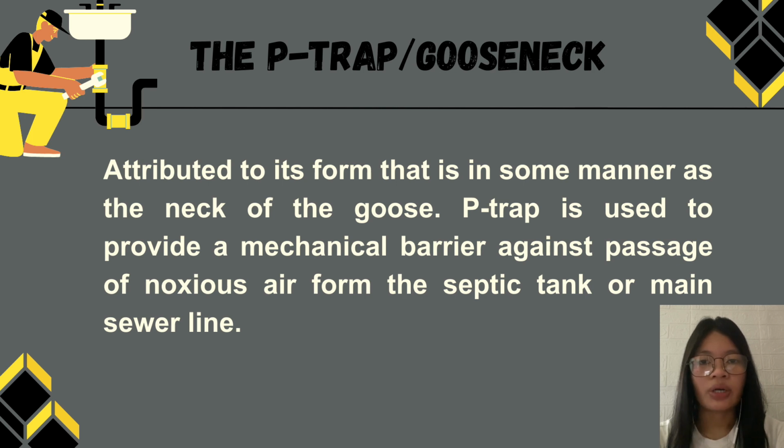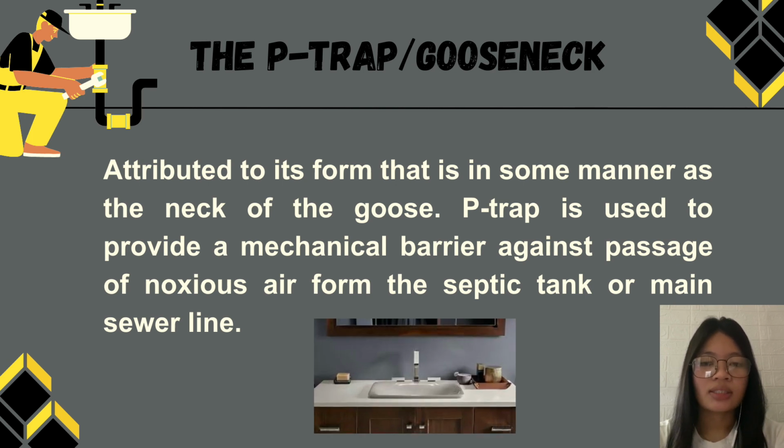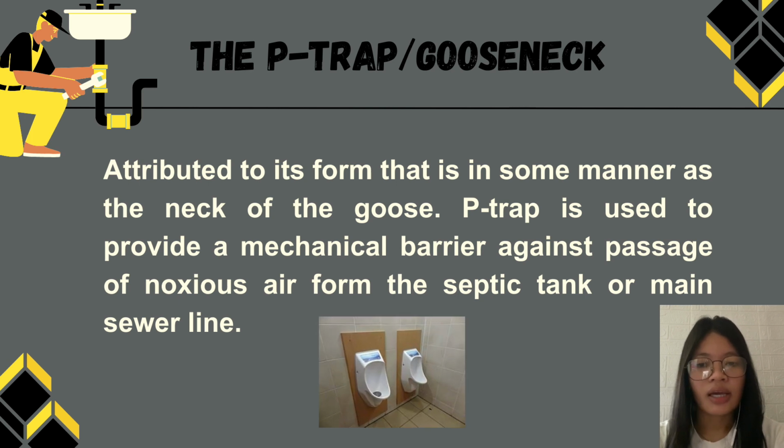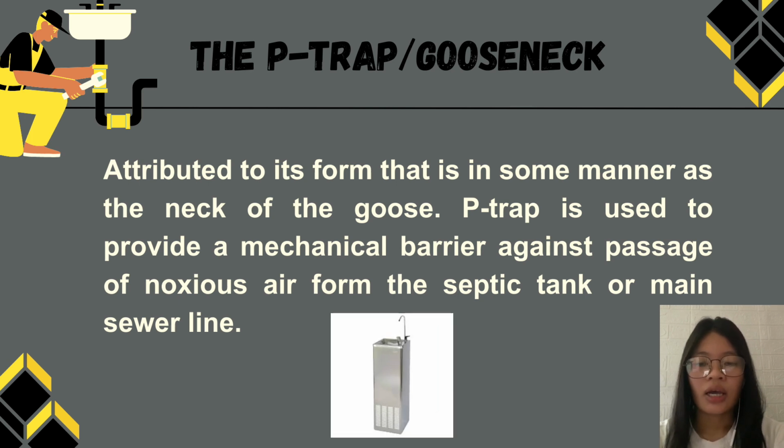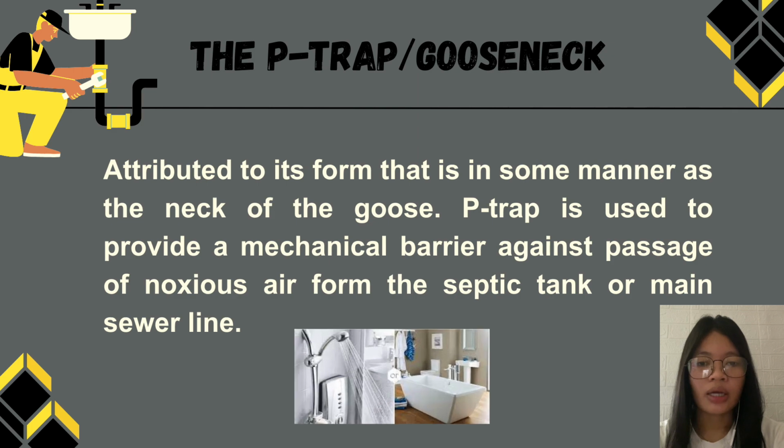Also, the P-trap is the most common and practical shape, available in various sizes from 32 mm to 50 mm diameter. These are common sizes for fixtures that are suspended from walls or supported on a pedestal, such as lavatories, urinals, sinks, drinking fountains, and the last one is the shower bath with less amount of water discharge.